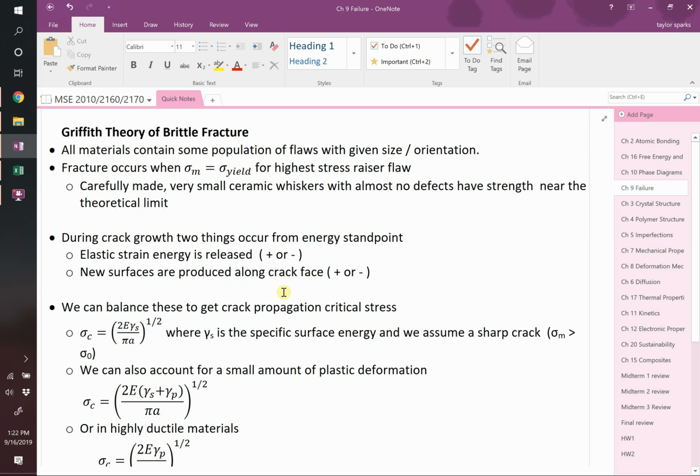But not all flaws are equal. The one on the surface that I did to this thing is going to be a severe flaw. It's going to make it break really easily. But if I put a little nick more on the edge, and I bend this thing just the same, then it's still likely to break in the middle for two reasons. One is that this is a bigger flaw, and the other is why? The bending moment increases until it reaches my thumbs. Then it has a plateau of maximum bending moment, and so this little flaw is in a region of small bending moment. So it has two reasons why it's not going to break there.